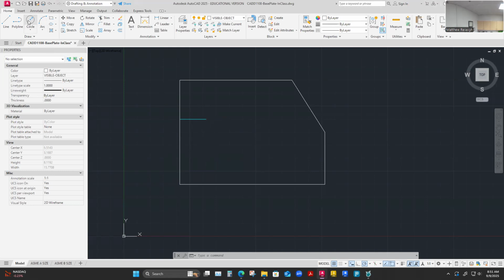I'm using a center radius circle, but it's okay because I can just go D for diameter and then I can hit that it's 1 inch. So I selected the endpoint as the center, then I entered D for diameter, and then I entered 1. That's just because I had picked the center radius circle selection. So now I need the other one over here. The other one is like 3 inches over and an inch and a half up.